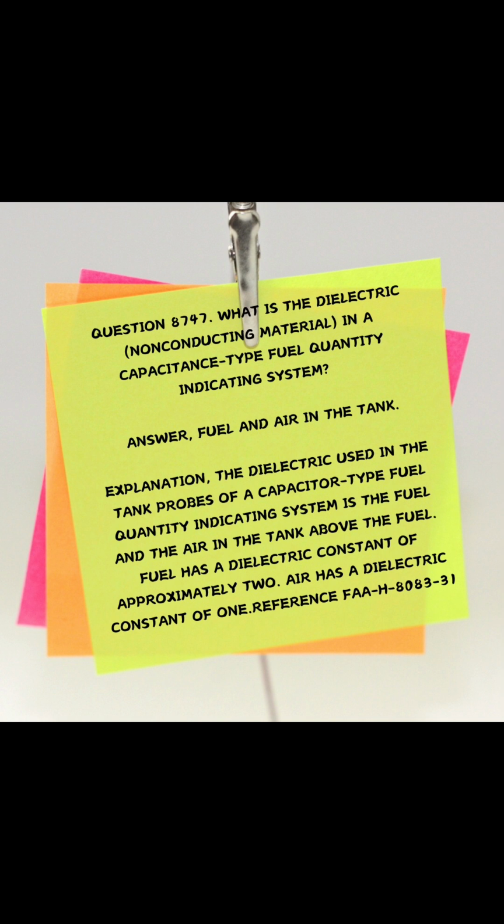Question 8747. What is the dielectric, non-conducting material in a capacitance-type fuel quantity indicating system? Answer: fuel and air in the tank. Explanation: the dielectric used in the tank probes of a capacitor-type fuel quantity indicating system is the fuel and the air in the tank above the fuel. Fuel has a dielectric constant of approximately 2. Air has a dielectric constant of 1. Reference: FAA H